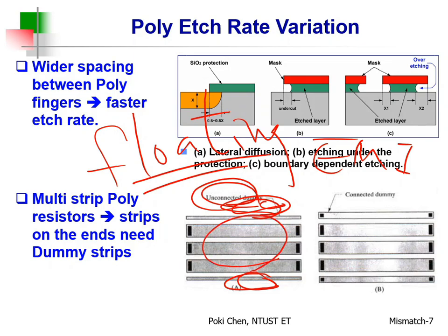To bother the real devices is no good. So you had better what? Shut them up. But how can you shut them up? Connect, the black one means contacts, right? So you can connect them to some silent source. Okay? Silent means what? Not so noisy. Clean. This is what I mean. So you had better connect them to clean ground or clean VDD.